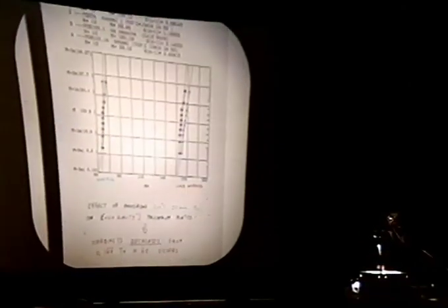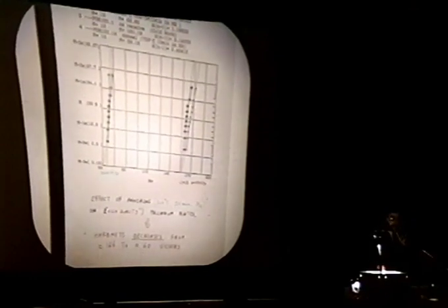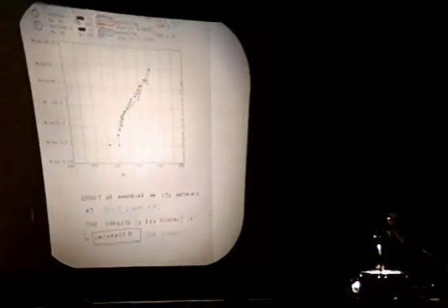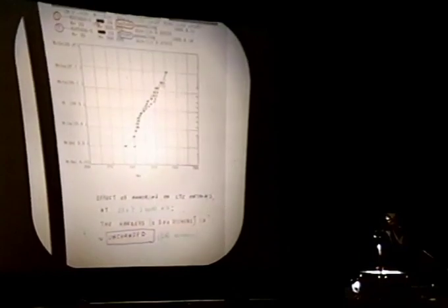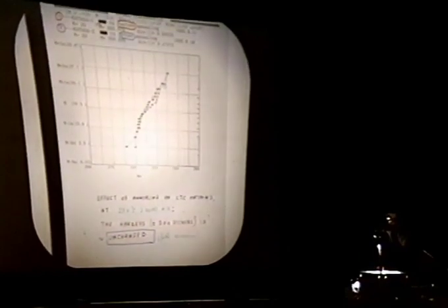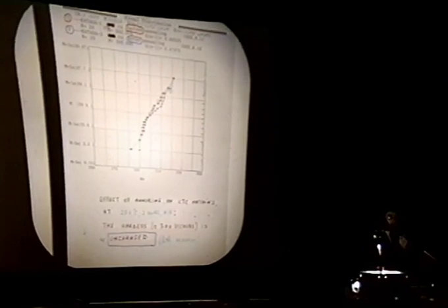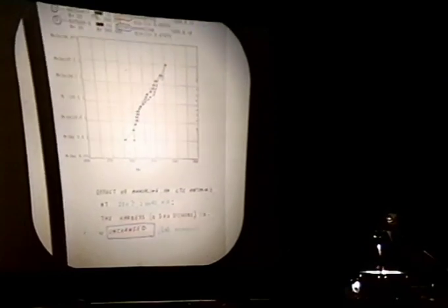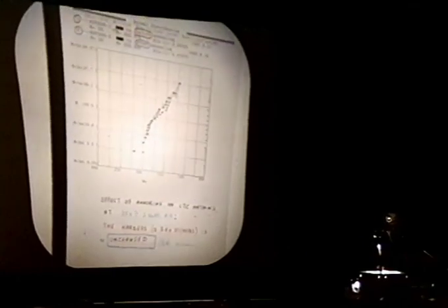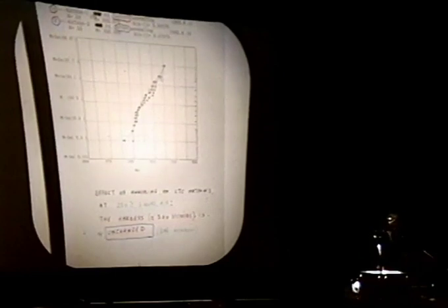This is the effect of annealing palladium. The hardness decreased from 160 up to about 60. So, following this idea, we developed, in a joint experiment, a new kind of palladium plate with additional standard copper compounds, and then we get hardness as high as 300.